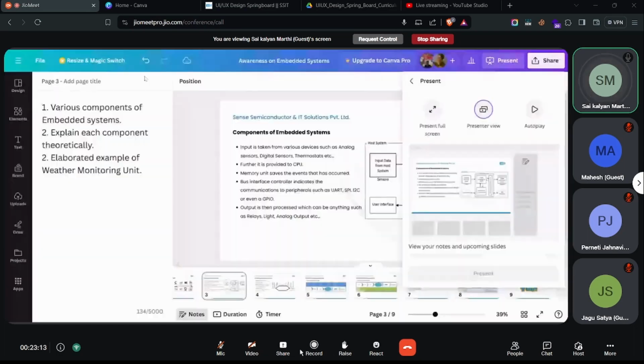Now that the system has requirements, we need to divide the hardware and software development. This is the critical part of any system development. We may have a requirement like monitoring CO, but to monitor CO we need a particular sensor, a particular interface to program, and particular hardware to communicate with that CO sensor. So how are we going to divide the hardware and software requirements? That hardware and software partitioning comes under phase two, where we take the requirements of the system or project and distribute what hardware we need to procure and what software components we need to write.